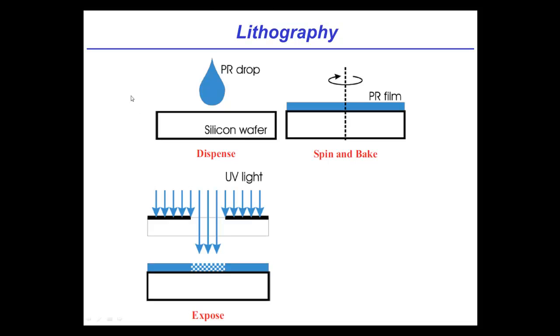The way we do that is, for example, using an optical lithography technique. So that's what I show over here. Here's what I do. I take a mask, and the mask is typically made of glass or quartz, and it has regions of chrome on it. So you can see I have a picture of a mask over here where I've got black chrome on the right and black chrome on the left, and in the middle I have an opening. And I hold that above the wafer. In a modern system, I'll actually use multiple lenses as well. And then I shine light through the mask.